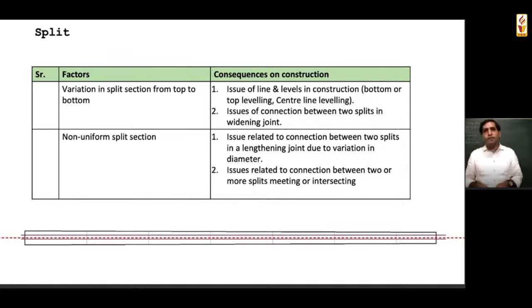Because what is going to happen is, if I have to draw for you, if I want to get a uniform section size like this, it means that I am removing some of this material. And why does it matter? Because bamboo is a linear fiber. In case of bamboo, you have to realize that the bamboo's strength lies in its circular form as well as its strength at the knots. At the knots, the fiber changes direction, and in the rest of the places the fibers are linear. So the moment you start cutting anything in the bamboo, you are removing the fiber of the bamboo, and you are weakening it. So you cannot treat the joineries of bamboo in the same way in which you treat timber or steel, because the moment you do that, the bamboo starts weakening. So the whole trick lies in using the knot, minimum cutting of the bamboo, as well as using its form.